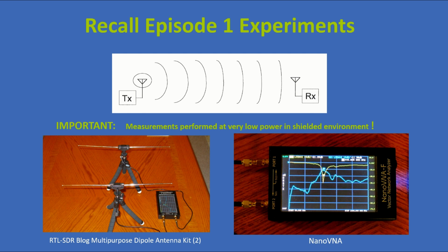And if we punch our calculator, we can figure out it's actually about a 16th of the power that was transmitted. So where did the other 15/16ths of the power go? Where did most of the power go? Well, it went out to other directions other than the direction where the receiver is.